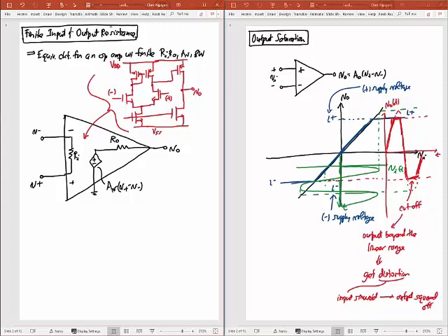So the Ri, the voltage-controlled voltage source, and the R naught, they're all just modeling what this circuit actually does. Okay, it's a simplified model, but it works quite nicely actually. It works so nicely that when we analyze a circuit like this in red, what we're going to try to do is pull out the Ri, pull out the R naught, pull out this voltage-controlled voltage source,